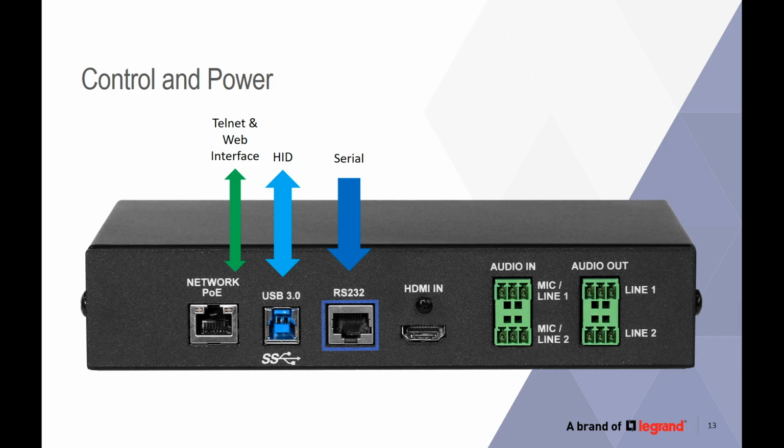For power, you might notice that this doesn't have a local power connector. It accepts PoE, not PoE plus. A lot of our products are PoE plus, like our cameras, PoE plus plus in the case of our UHD big, heavy block cameras. This is because there's no motors that need to be driven. It's capable of being powered by PoE, and a PoE injector does come with the unit, but if you did want to just hook this up to your switch that provides general PoE, you don't need one of the more powerful ones that will provide PoE plus, or worry about your wattage management on that kind of thing, because PoE is very easy, nice and simple.